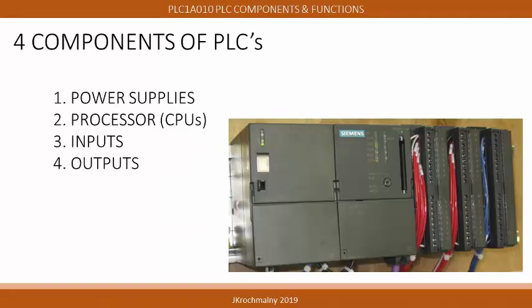As previously mentioned, PLCs come in a variety of sizes and complexities. The common things about all programmable logic controllers are that they all have power supplies to provide assembly power, processors to provide the intelligence of the system, inputs to gather the conditional information, and outputs to control devices serving that condition.